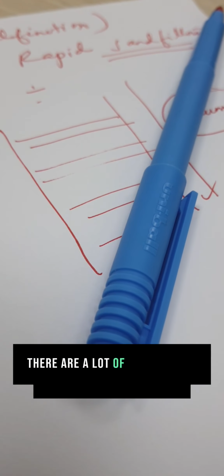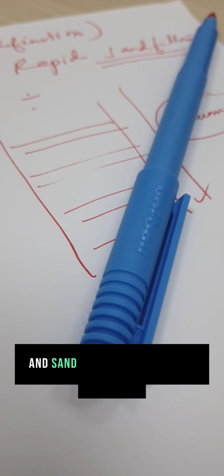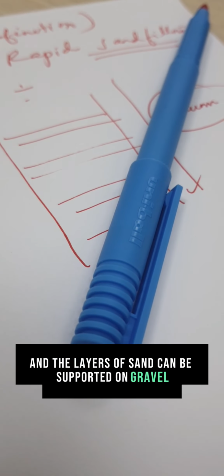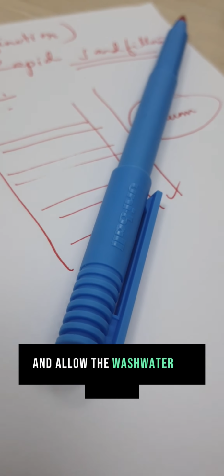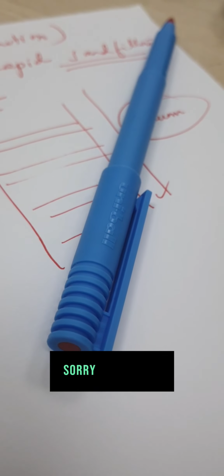There are a lot of filter media available in the market. We have sand, and sand can be either fine or coarse, so they are called filter media. The layers of sand can be supported on gravel, which will allow the filtered water to move freely to the underdrains and allow the wash water to move uniformly upward.